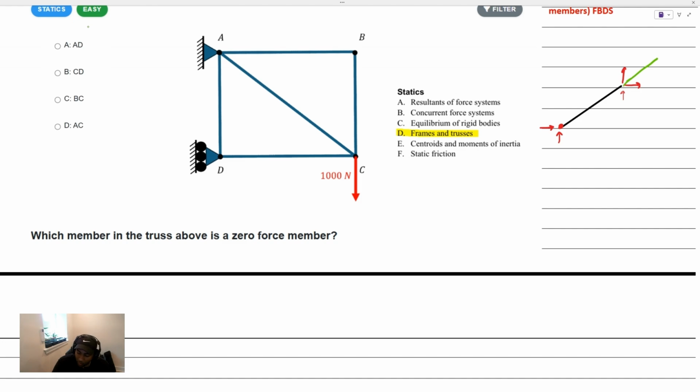And what about the sum of the forces? The sum of the forces tells me that if this force is pointing along this line here, like this, and we assume it to be outward, that means that the force at this joint must be equal and opposite here. So you can kind of picture that if you have a two force member, which means that it's pin connected at both ends with no forces in the center of the body, we'll have to have these forces pointing directly away from each other or directly towards each other. And it kind of has to be in the direction along these two pin supports here, right? So that's the idea of a two force member.